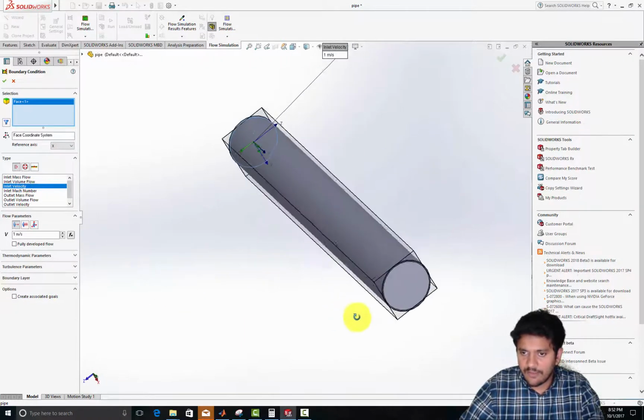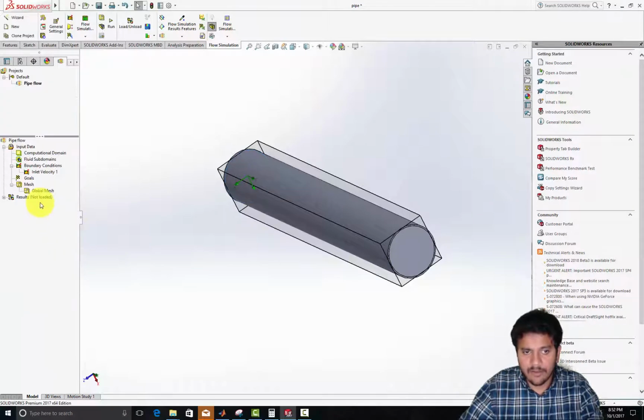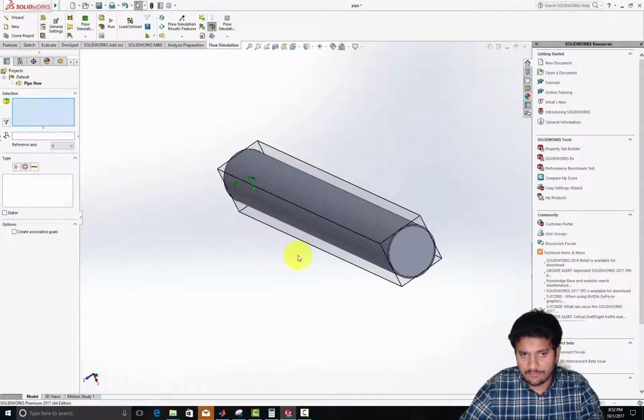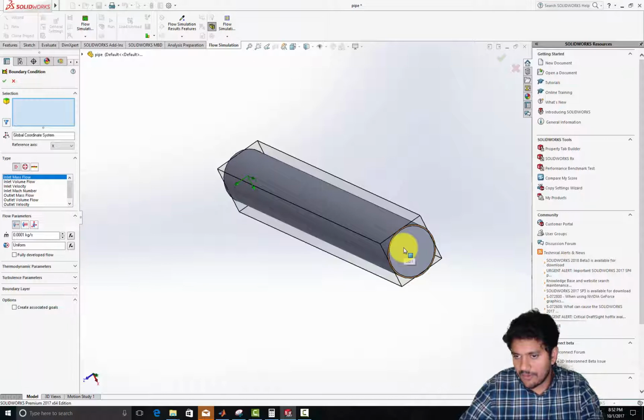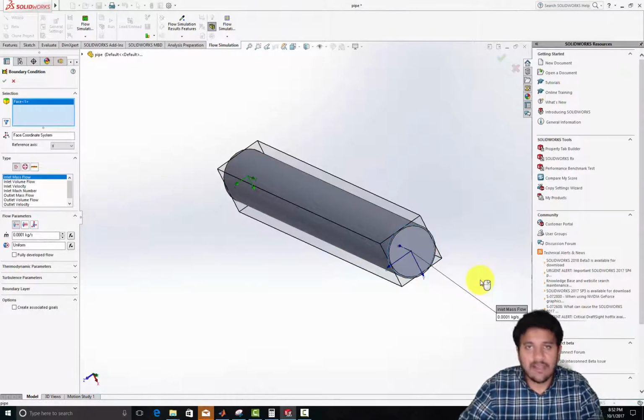And in the next phase, let's just click OK here and do the same thing again. This time I'm going to right click on the other face, click on select other, and make sure that you select face at lid 1, and in the bracket you see pipe. Okay, so that's the name of your simulation, right? That's the name we gave initially. So you need to see that name, okay? Whatever name you gave, make sure that you see that. Do not select this option, that's the wrong one. In a later video, I'll comment on why that's the wrong option.